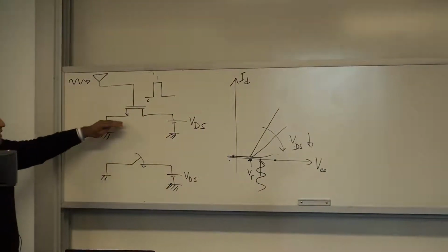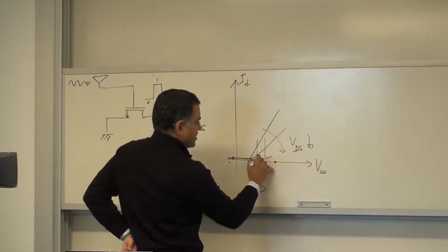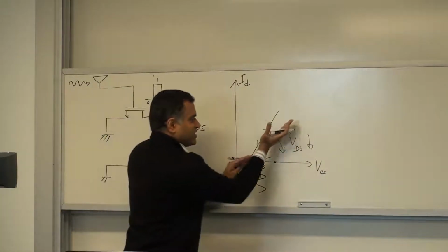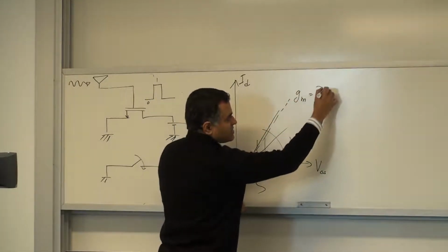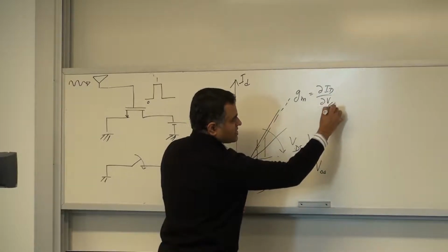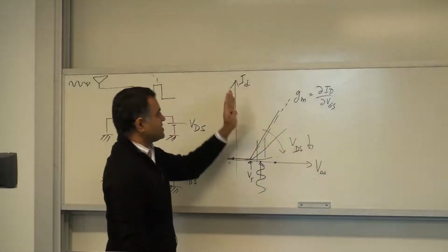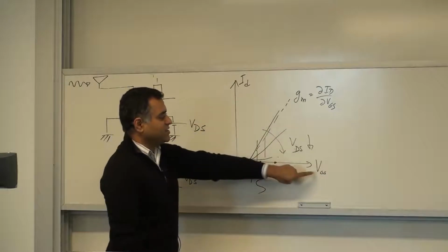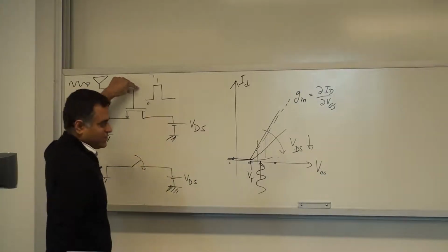And then you can see that if that happens, your current will actually change by quite a bit. The current starts depending upon how much. This slope is called the gain, or the transconductance, GM, which is the derivative of drain current over VGS. Transconductance, because it's not drain current versus drain voltage. If it's ID versus VD, that would be just conductance. But ID versus VG is a third terminal, not in the path of the current. So that's why it's called transconductance.